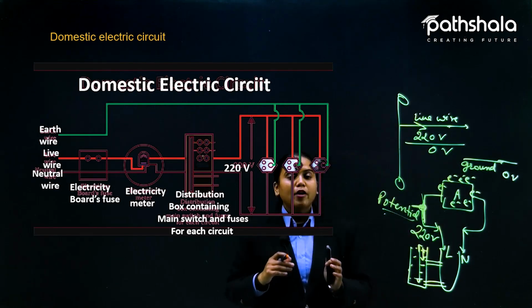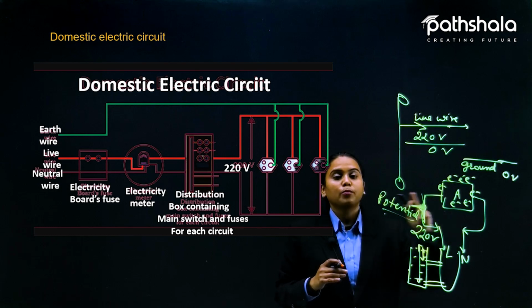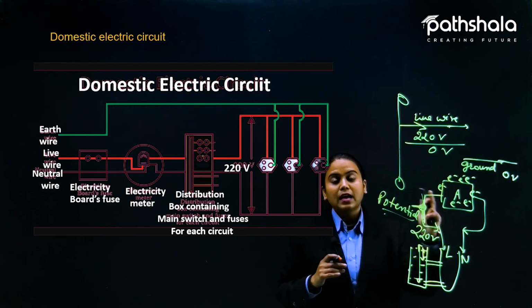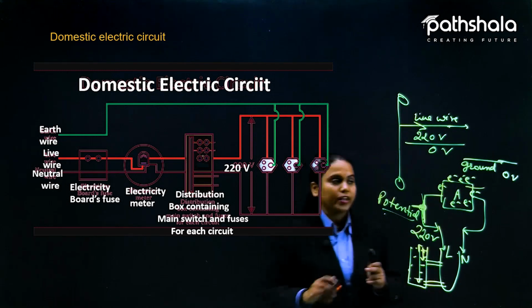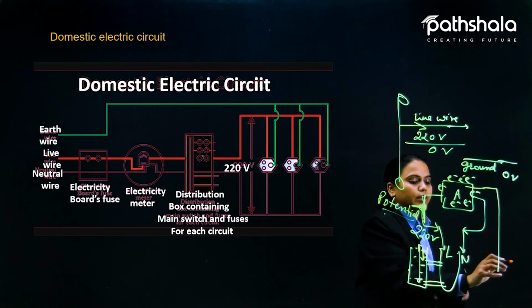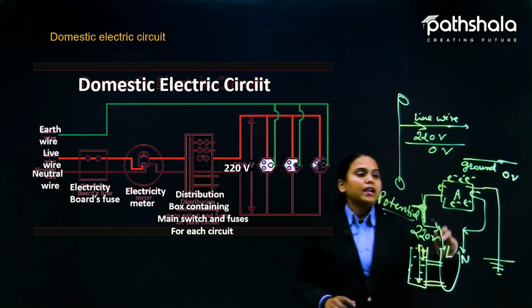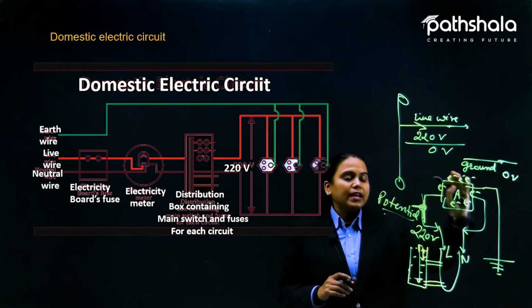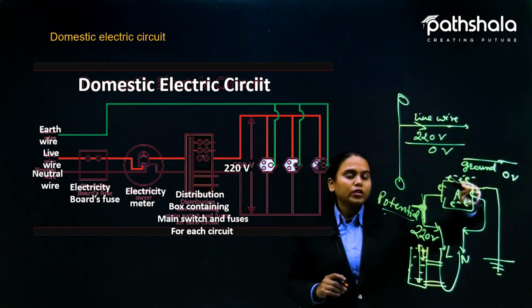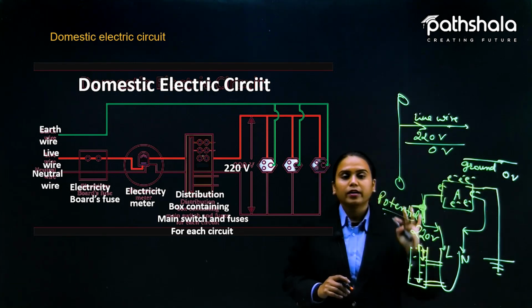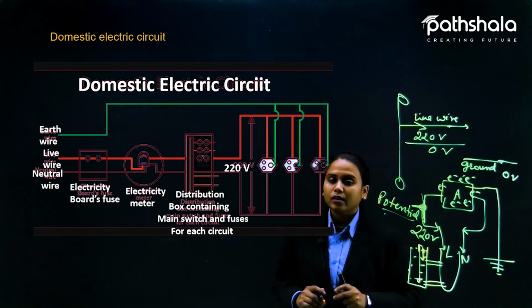Okay, that is why we can protect ourselves by keeping the appliance attached to one of the wires that is attached to its body, and we put it into the ground like this, so that if by chance any electrons collected over the surface of the appliance get through this wire and go into the ground easily. So this is known as earthing.